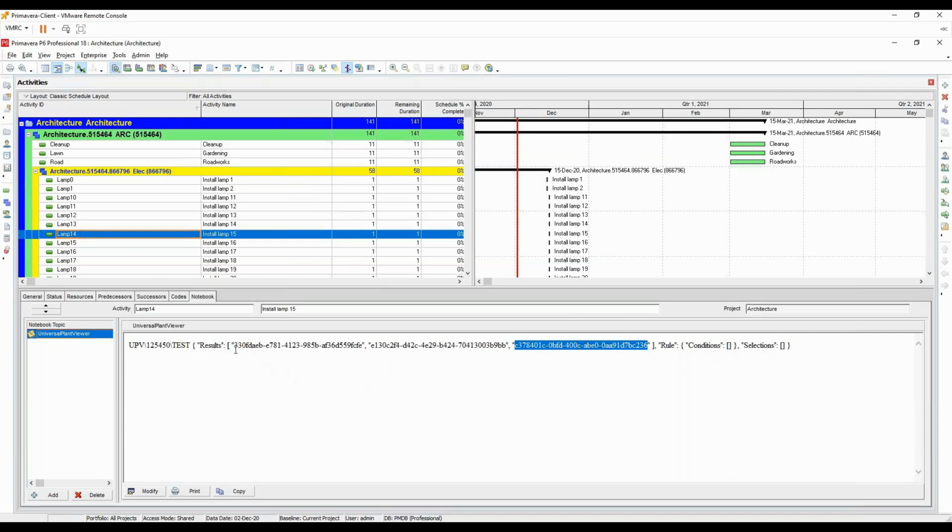So it could add 500 items today, 500 additional ones tomorrow, and then somebody deletes all pipelines. So in a couple of days from now, we would have a result of exactly 0 items in here. That is something dynamic, so you can really work with your 3D model, and this tool can help you to update the information from the 3D model here in the database.